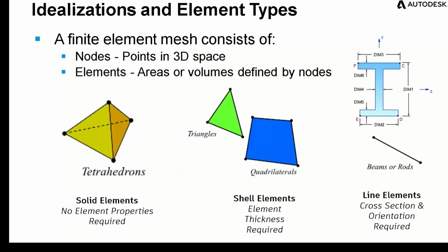With the way FEA software works, it breaks down your model into a series of elements, and what kind of element we're going to deal with determines what result element you look at. For a solid model, we're typically working with some type of tetrahedron shape, a three-dimensional pyramid type shape. If you look at a surface model, that's classified as a shell element. Shell elements are planar surfaces, 3 to 4 points. I think 7 points is the max, if I remember correctly.